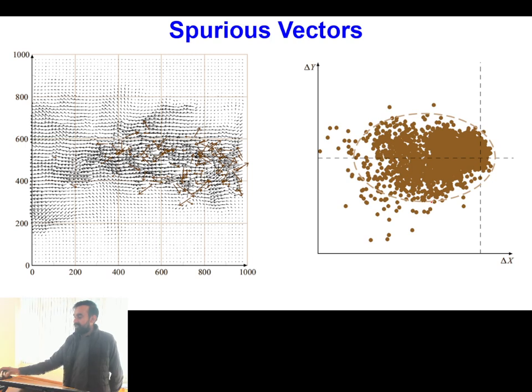Now this is the important point I mentioned about the spurious vectors. Here you can see in this grid all these black colored vectors are our physical velocity vectors, and these yellow colored long velocity vectors are our unphysical or spurious vectors, which have come because of errors in our measurement. So here you can see how to differentiate the behavior.